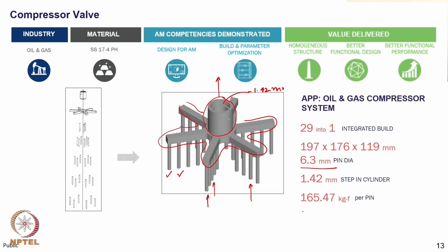These pins are required to carry substantial force, 165.47 kilogram force. There are 29 parts which can be built as an integrated part using additive manufacturing. The size of this particular geometry is 197 by 176 by 119 mm.